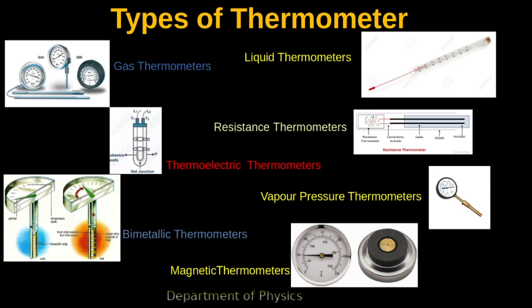Which liquids are used in glass thermometers? A liquid in glass thermometer has a bulb with a long capillary tube of uniform and fine bore. A suitable liquid is filled in the bulb. When the bulb contacts a hot object, the liquid in it expands and rises in the tube. The glass stem of the thermometer is thick and acts as a cylindrical lens. This makes it easy to see the liquid level in the glass tube. Mostly mercury and alcohol are used in glass thermometers.